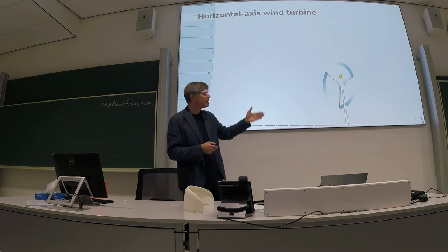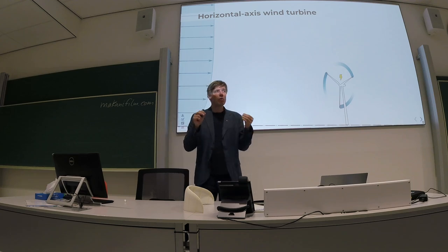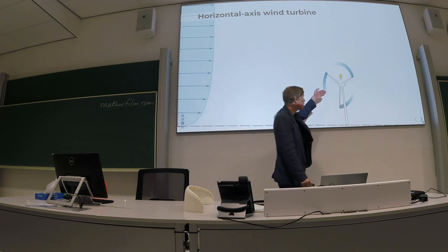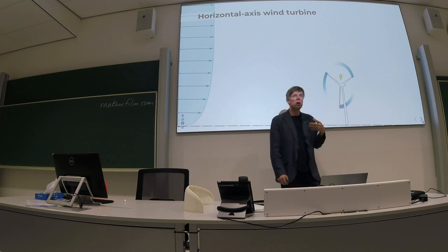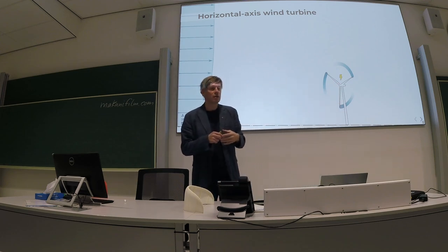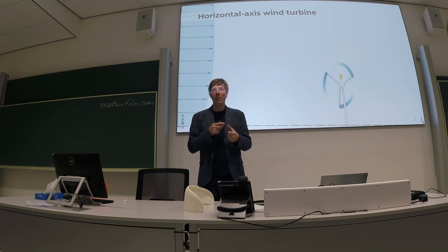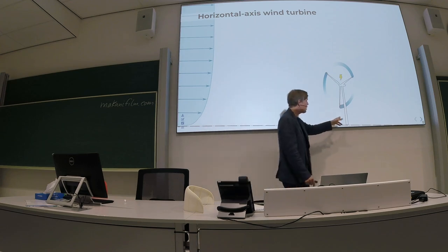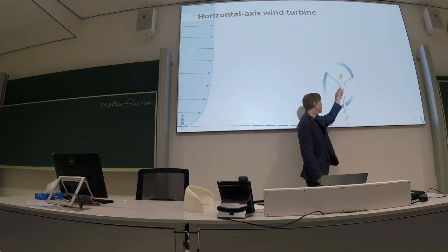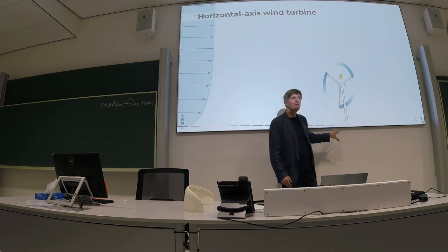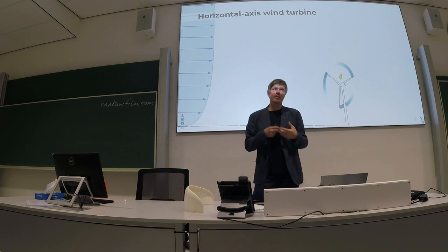What's specific here is the motion of the blades is constrained. This entire rotor can just rotate around the hub. And that mechanical constraint requires quite a lot of mass and structure. You need a tower, you need a quite good nacelle, you need rotor blades that are very strong at the base, and the tower needs to go into a foundation which is quite massive.